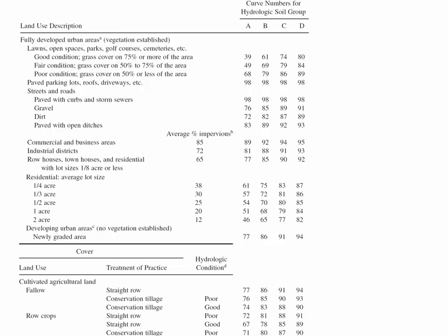That's true. Really, runoff for us is a problem. All we see when we see runoff is damage to structures, expensive big pipes that have to be put in. So really, the engineering perspective is that this runoff, the storm water, is kind of like waste. And we would prefer that there's as little of that storm water that has to be accommodated as possible. And so that's why we call C and D, we think of those as kind of bad, unfortunate soil types.